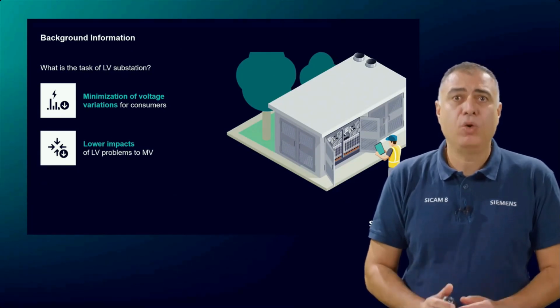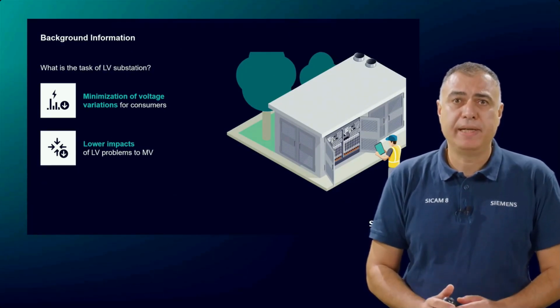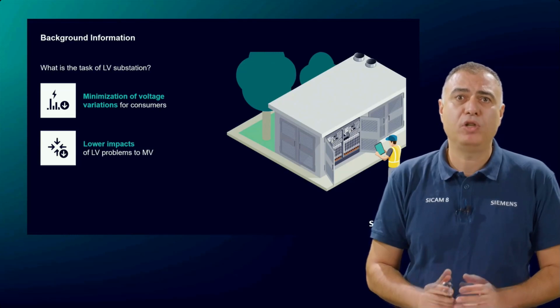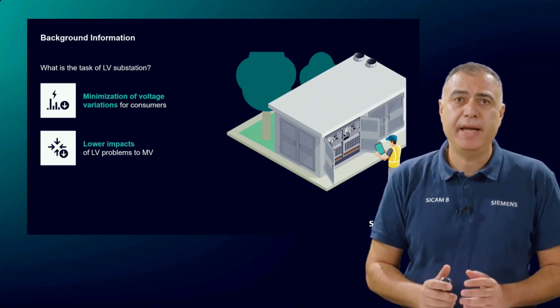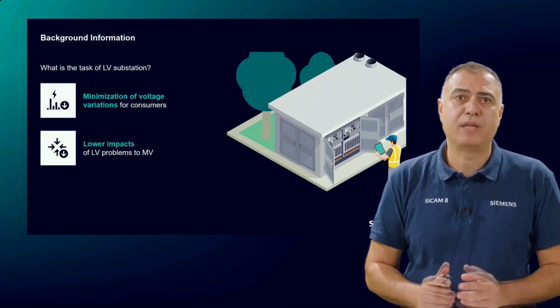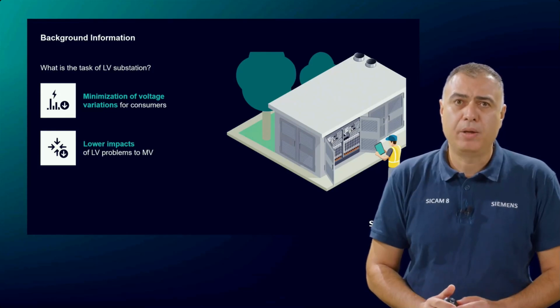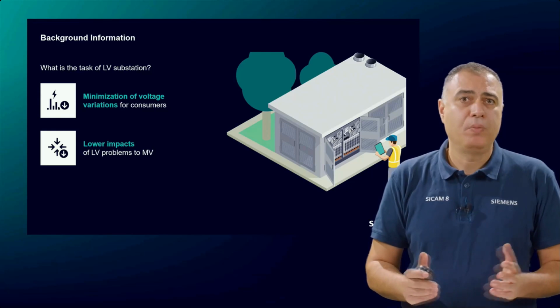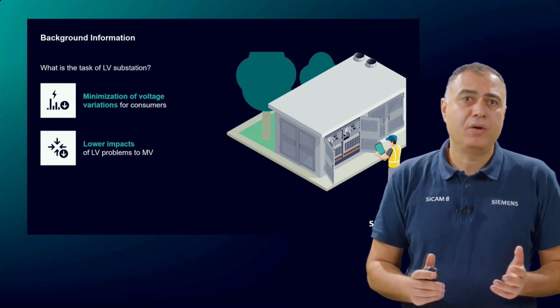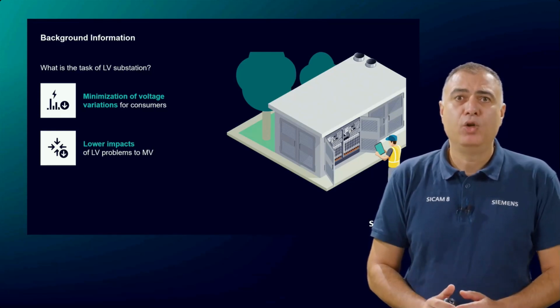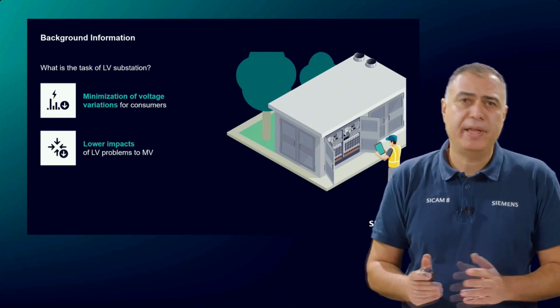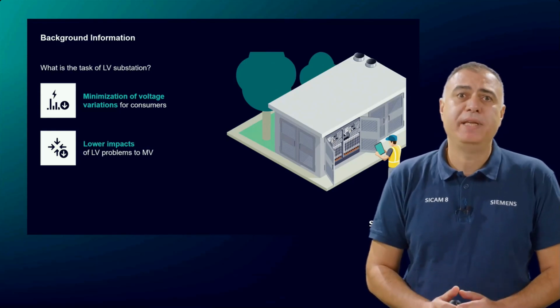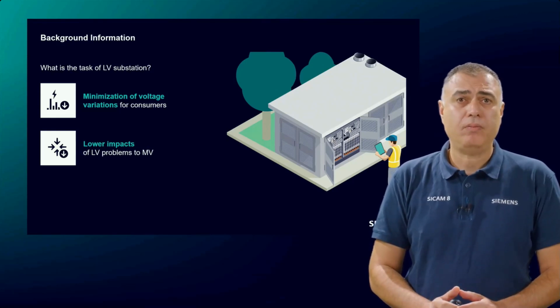One major goal of the low voltage distribution grids is to keep the voltage for end users here in Central Europe as close as possible to 230 volt AC. Maybe you know that there is a 2009 agreement not to deviate more than 10% from this nominal value.